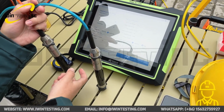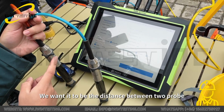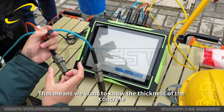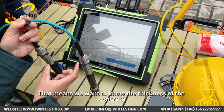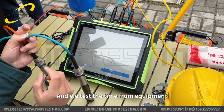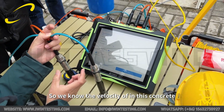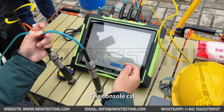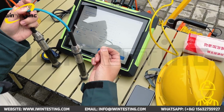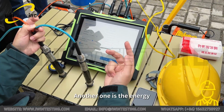The span is the distance between two probes. That means we want to know the thickness of the concrete, and we test the time from the equipment, so we know the velocity of this concrete. The CSL final results we get: one is the wave velocity, and another one is the energy.